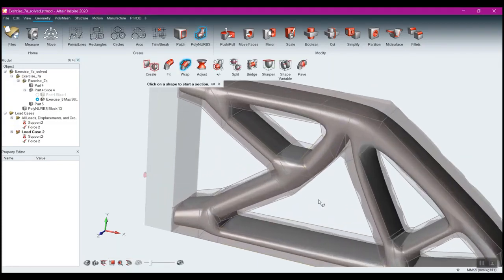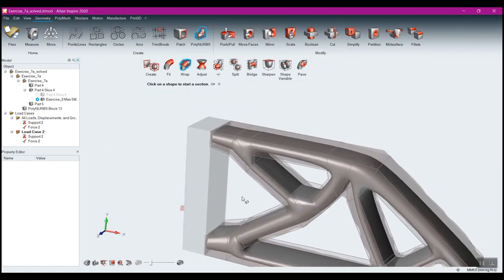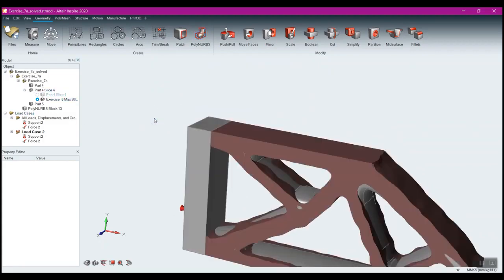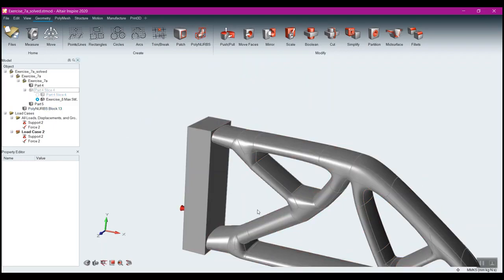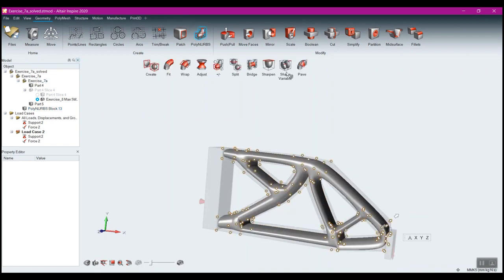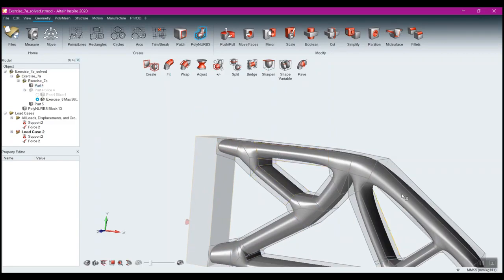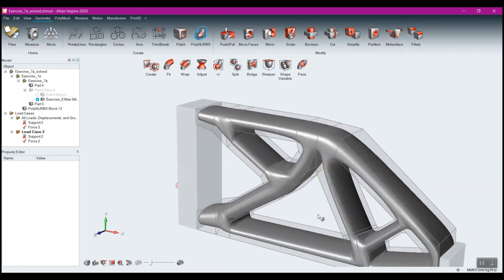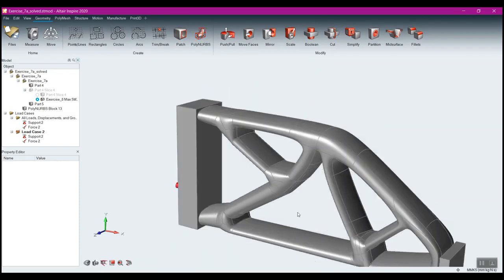When I've completed all of the bridging and the wrapping, I end up with a part that looks like this, and we can exit out of the polyNURBS, turn off that, and you can see we have this part here. And just like I said, we can opt to go with the medium sharpening on this. Oh no, actually I can't sharpen it anymore, because once I do those Boolean operations, that eliminates that ability. So the Boolean operations are what you're going to want to do absolutely last. But that's how we can go about creating the polyNURB geometry directly within Inspire.